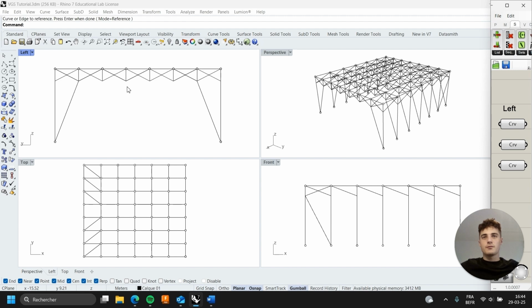So let's start with our initial truss that we can see in the right view in the ZY plane. This type of truss is called a thin truss. And we've added a vertical bar to this truss to turn it into a portal frame there. So this truss will support vertical loads. And we notice that we added two diagonals to build the frame and brace the structure. This allows it to withstand the lateral forces in the y direction, as for example wind forces.